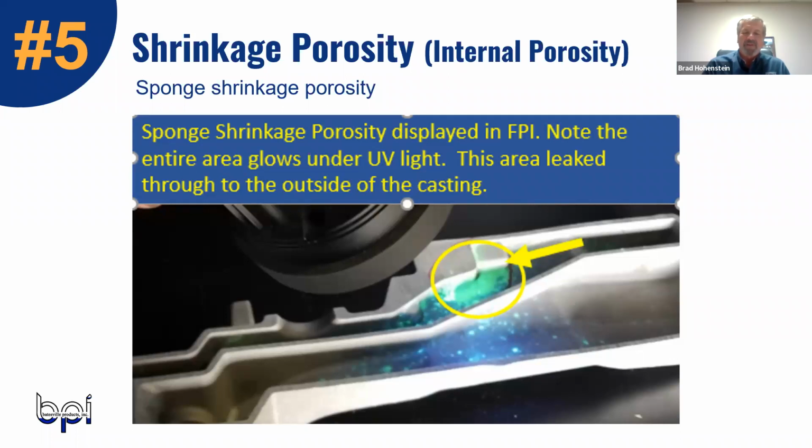It depends on the issue, because the taller the riser, the more pressure you're going to have on that metal filling, so you're going to be able to pressurize that casting. If more pressure of the molten aluminum is going to fix your issue, you go higher. If you need to feed it faster, then the wider riser is going to help you there. So it depends exactly on the type of casting, as Monty said.